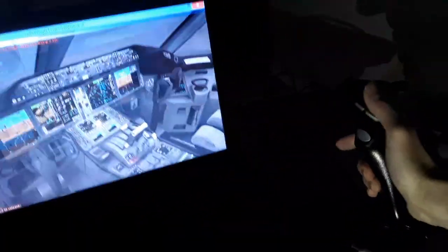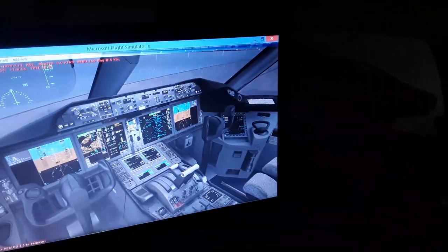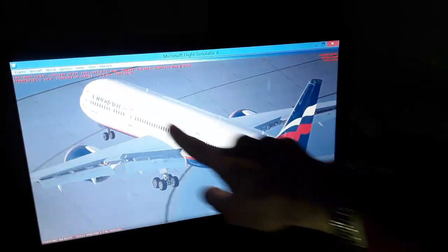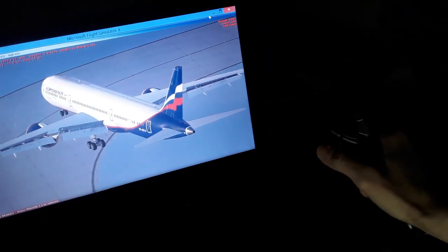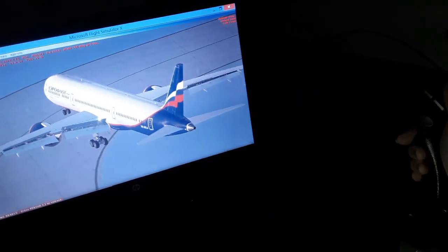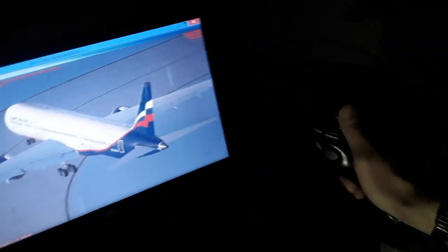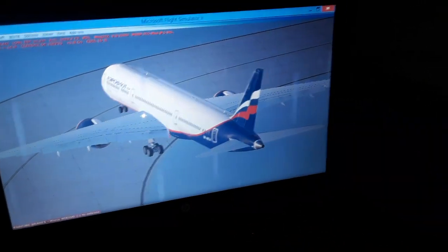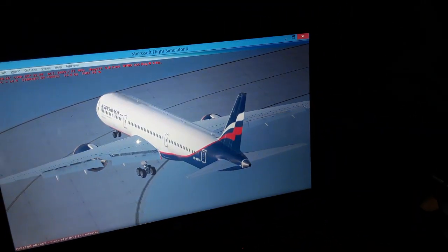The aircraft flight controls. So we have one more axis here. This is the longitudinal axis from nose to tail of every aircraft. So you make left and right side stick in the Airbus. You move the ailerons and the spoilers, and you make left and right turns. This is the roll axis, the longitudinal axis of the aircraft. You make left and right side stick deflection in the Airbus. In the Boeing, you control aileron, spoilers, and also the flaperons here, left and right flaperon, one extra flight surface.